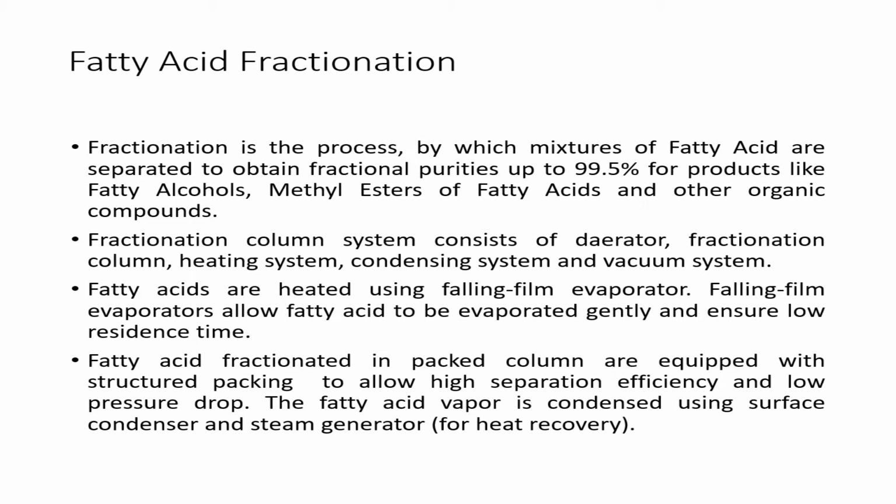Fatty acids are heated using a falling film evaporator. Falling film evaporators allow fatty acid to be evaporated gently and ensure low residence time. Fatty acid fractionated in packed columns is equipped with structured packing to allow high separation efficiency and low pressure drop. The fatty acid vapor is condensed using a surface condenser and steam generator for heat recovery.